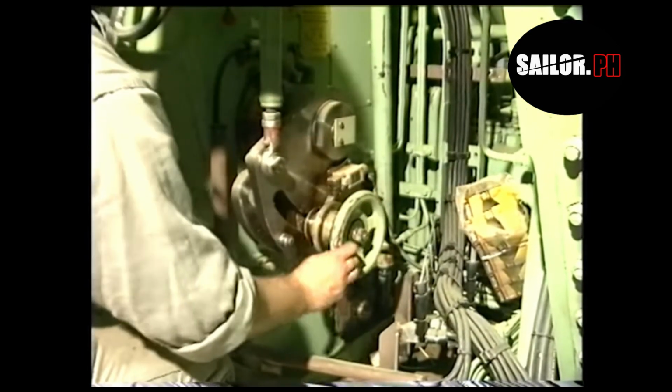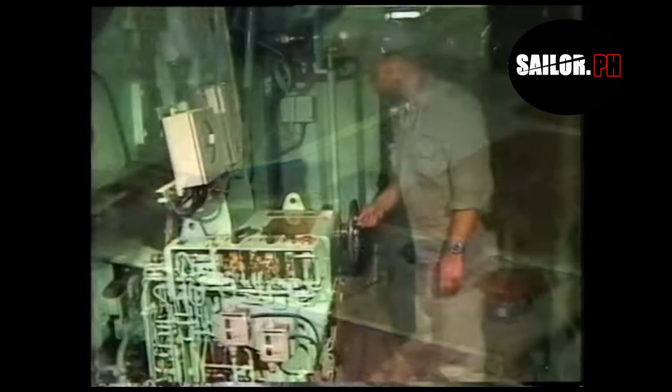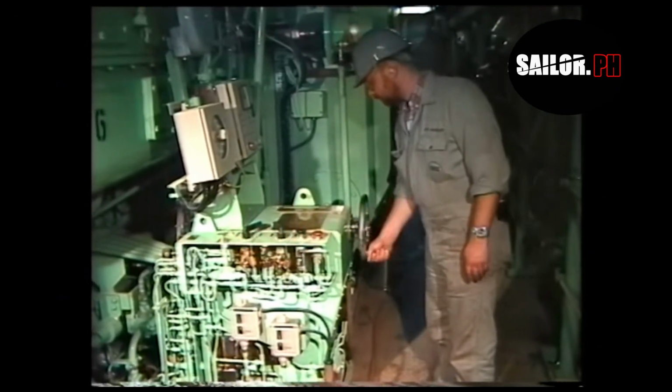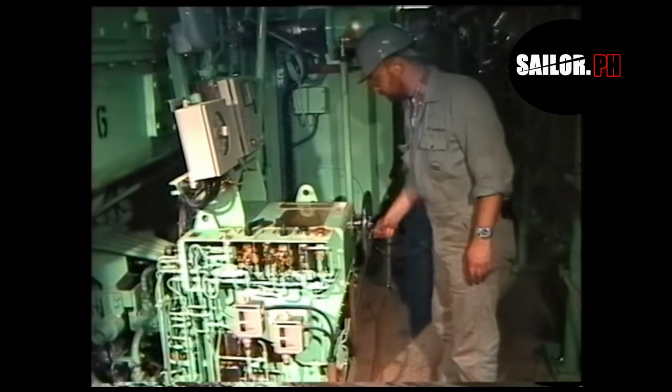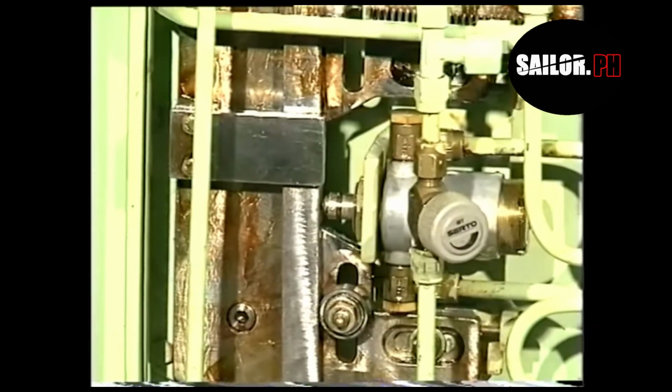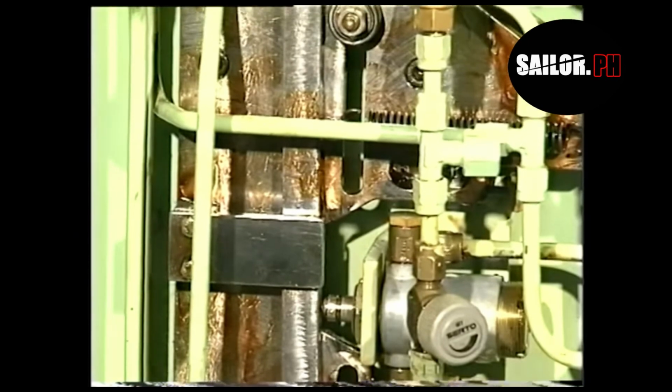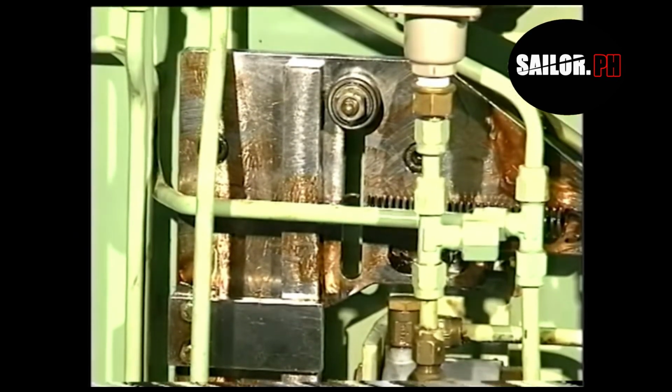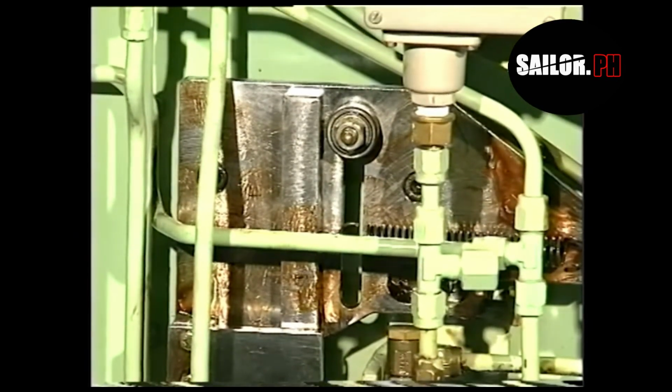Switch from engine room control to control from the engine side console. Turn the fuel regulating hand wheel corresponding to the determined fuel pump index at brake point. If the steel rod does not touch both pivoting points, loosen it from the shaft and turn it to the correct position.